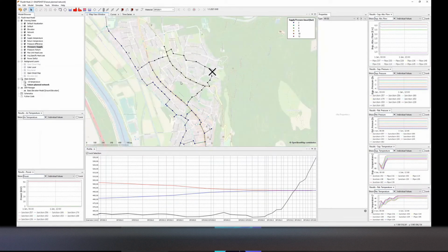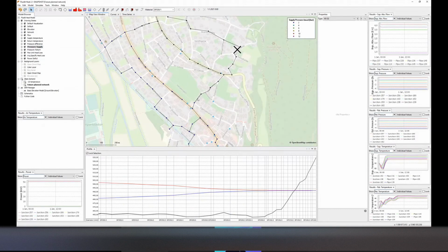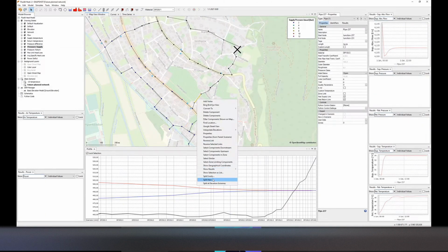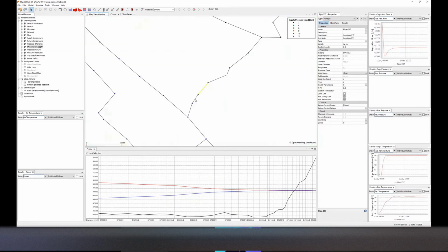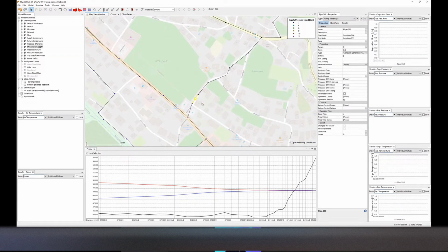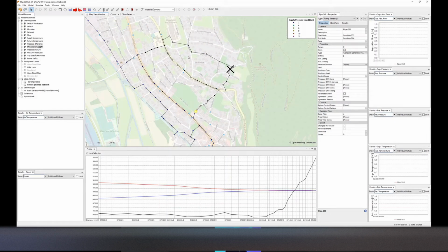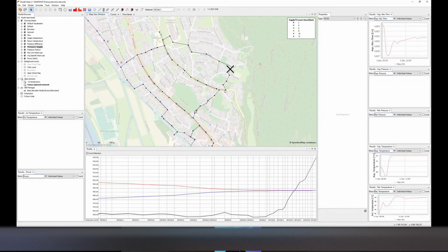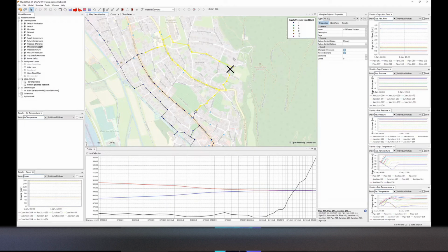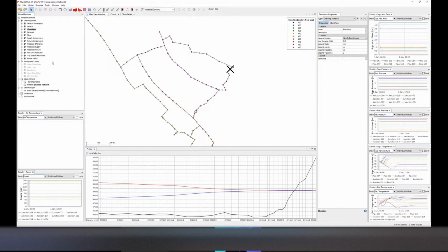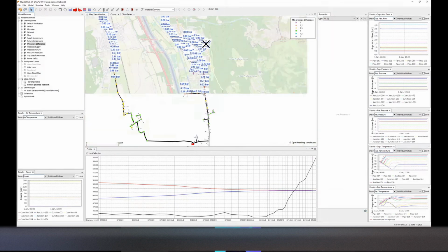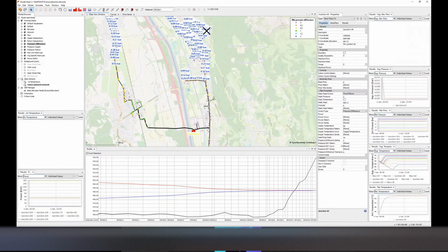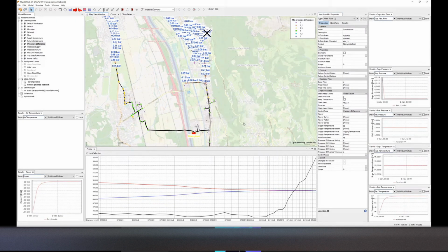What we would have to do is then create a new pressure zone. For example, I'll split this pipe and I will make this into a pump battery. So this pump battery will now be pumping supply water into here. And if I close this, I have a new pressure zone here, which is the highest elevation area. So there's quite a bit of problems there. I have a solution for that also that we will go into once we fix just this.